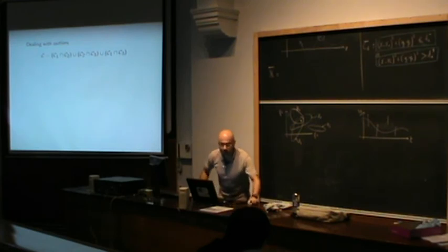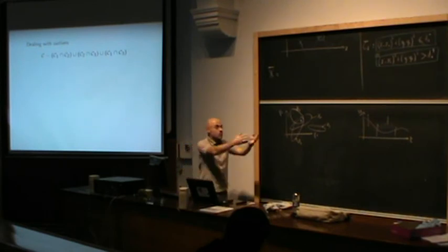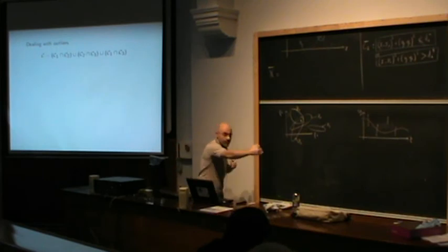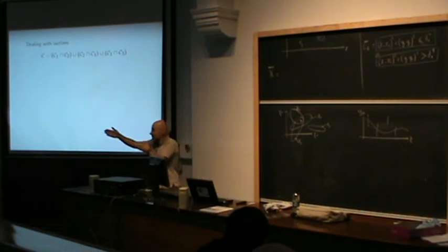So why is it important in practice? Because when a robot is moving inside an uncertain environment, it is supposed to measure distances, but when you measure distances, some people are going just in front of the robot and you measure another distance. When you use a sonar approach to measure this distance, you will have some kind of specular reflection which gives you another distance.